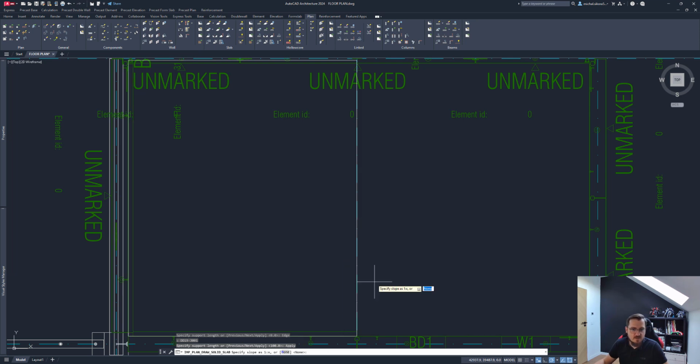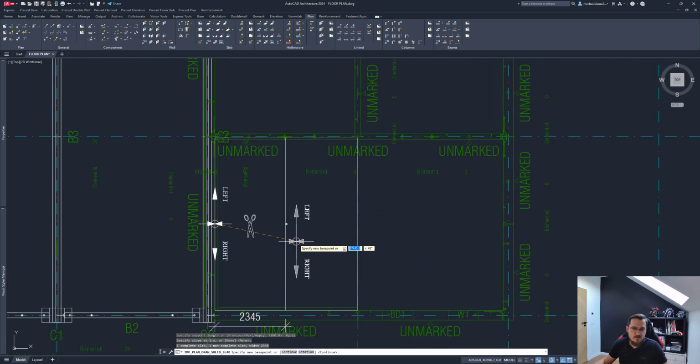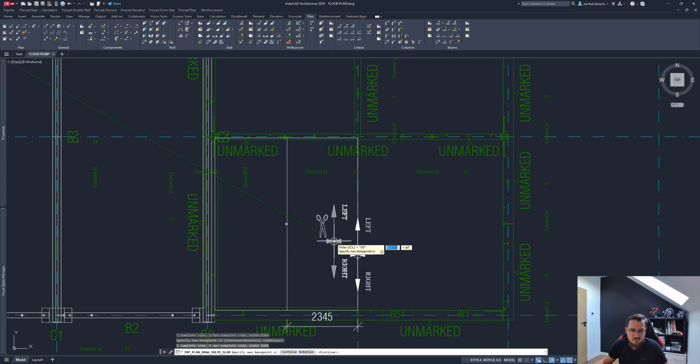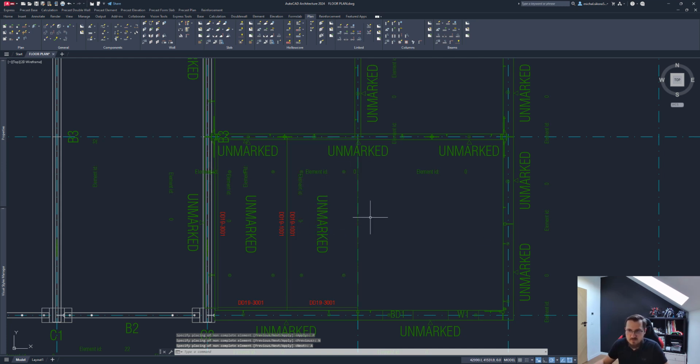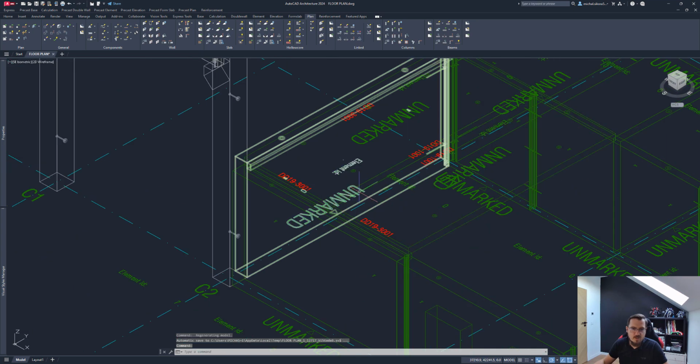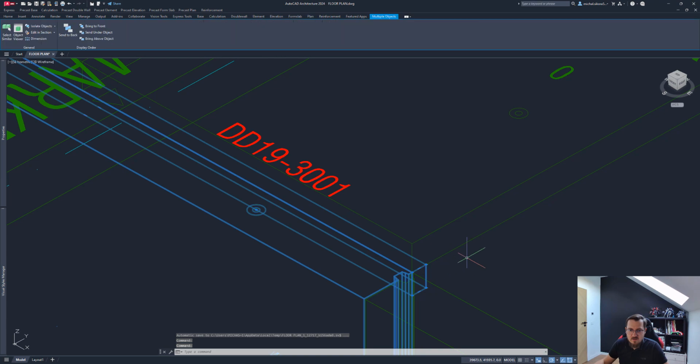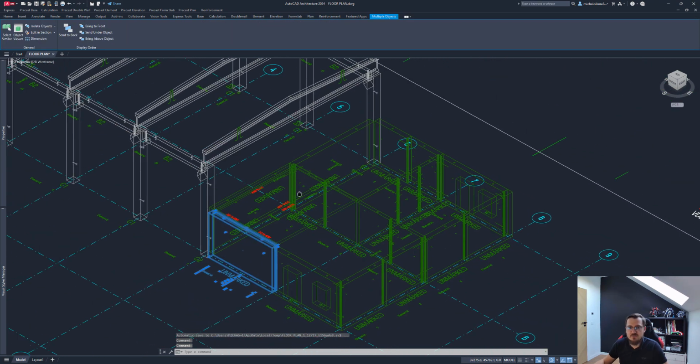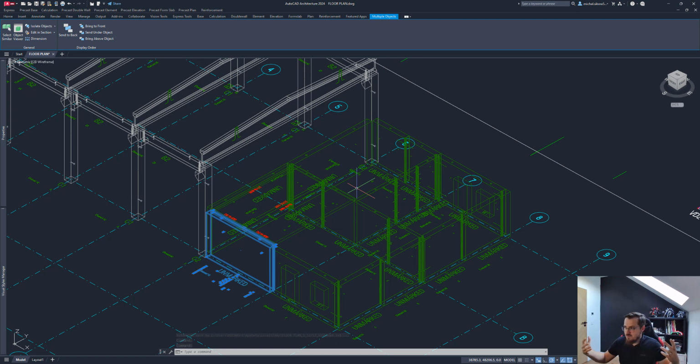And let's accept that. I don't want a slope, and I can now divide that slab, or if I want I can rotate that, but of course we don't want to rotate this slab because there's no support on this end. Let's do that and accept that. I can of course move the cut edge if need be. Let's make it that free slab, and like that it's all good. If I go to the 3D model, it's placed on our thickenings for the panels, right? Yeah, so that's the gist of it, of very quick modeling.